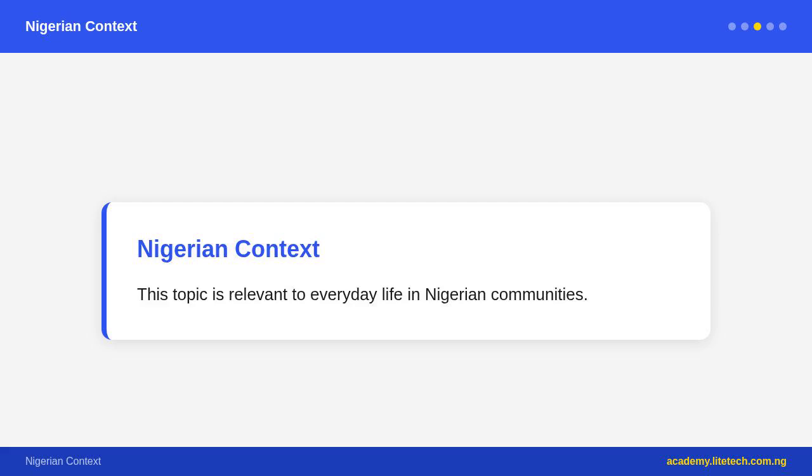Processing of aluminium. Aluminium comes from bauxite ore. Bauxite is first processed chemically using the Bayer process to produce aluminium oxide, also called alumina. Then alumina is melted and subjected to electrolysis, where electric current is passed through it to separate pure aluminium. Aluminium requires very large amounts of electricity to process, which is why it is called an energy-intensive material.